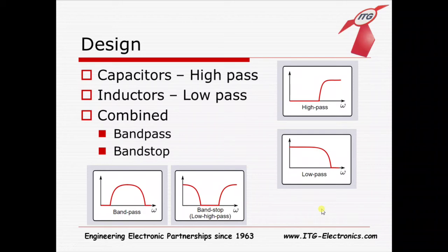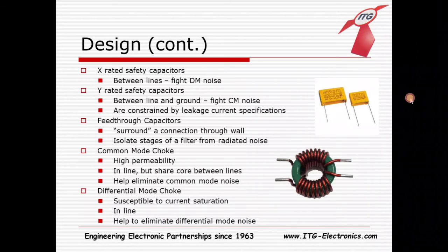So those are kind of the four classifications of filters, and they're going to be sort of combined in some way in whatever filter you're using. Typically, you'll see a low pass filter contending with EMI because most EMI noise is up in the higher frequency range. So as I had mentioned before, there's a couple of different uses for both capacitors and inductors in filters.